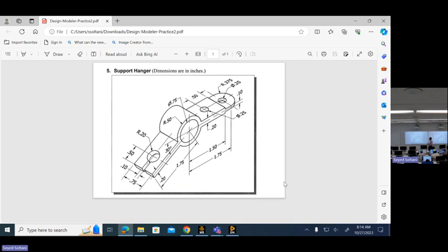But when I do that, I would like to do the extrusion in two directions, so it would be symmetric in both directions in Ansys Workbench, and each extrusion would be half of the depth of extrusion, so half of 1.75, 0.875. Then I'm going to take care of the rest. So this section would belong to the XY plane.